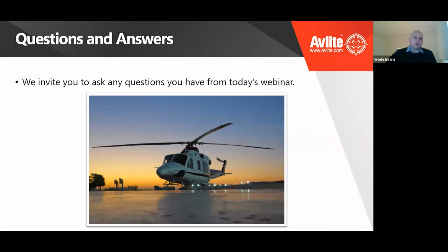Rather than trying to protect the lighting fixtures themselves, you're trying to protect the impact of that down to the much more expensive distribution infrastructure. So we've certainly done that. We've done a lot of those implementations now, where we've catered some type 2, type 3, and even type 1 surge protection into various helipad installations.